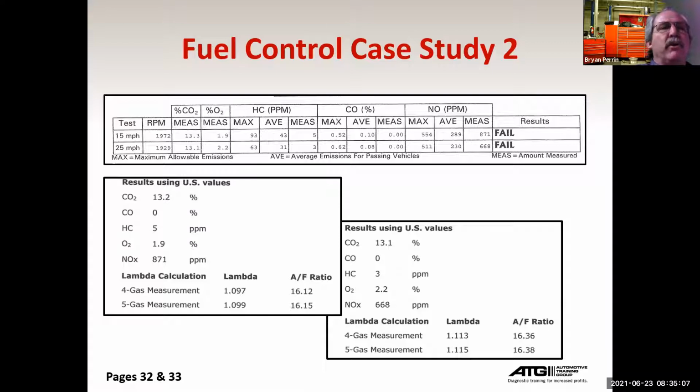Now we're down to sensor priority. Well, how many sensors does this car have? I have a MAP sensor. I have a TPS sensor. I have an engine coolant temperature and an air temp sensor. And that's about it, plus the O2 sensor. So now I'm down to, maybe this one had a mass airflow. I think this did have a mass airflow. But anyhow, I'm down to testing the load sensor and testing the other. So I'm going to test whatever's easiest, right? So I test the mass airflow sensor. I'm testing these. I get to the TPS and I test it, and it's in spec